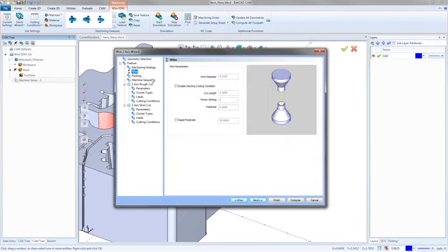For the wire, you define the wire primarily by right-clicking on the tool steel over here and then modifying the wire diameter. But I'm all right with a 10 thou wire. The enable starting cutting conditions are cutting conditions specifically for your lead in. So it's when you're first entering into the material. And then you could also set up a rapid feed rate, just so you can override your feed rates and have that rapid feed rate output.